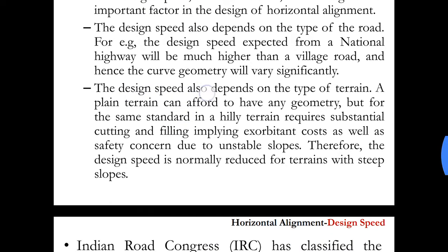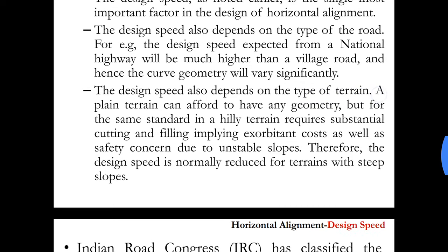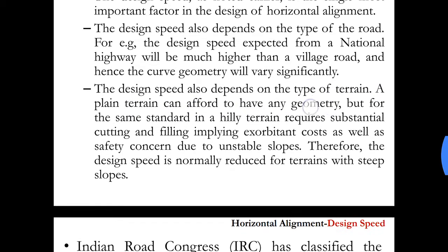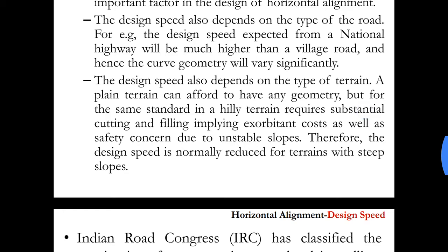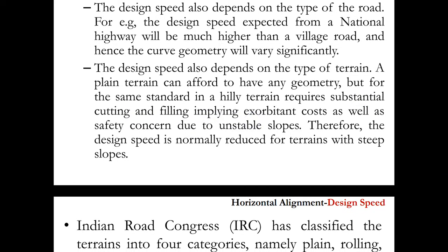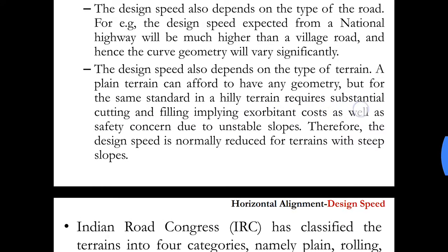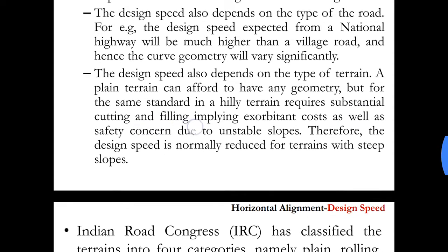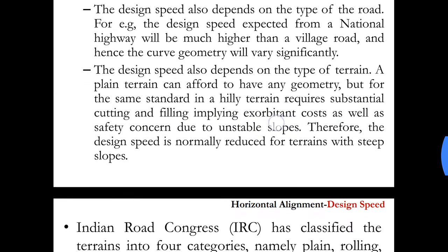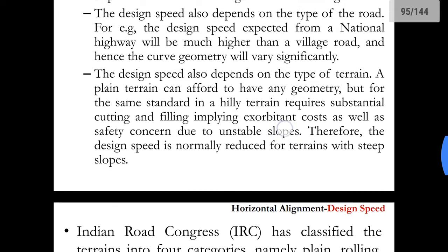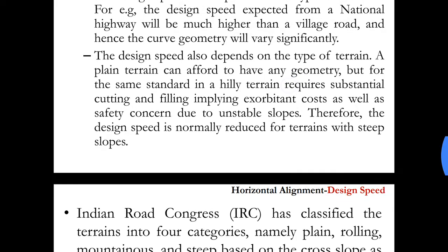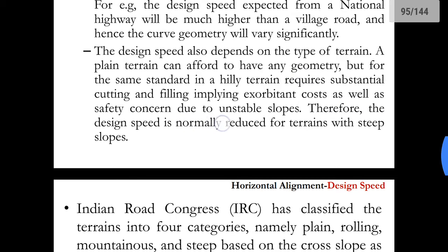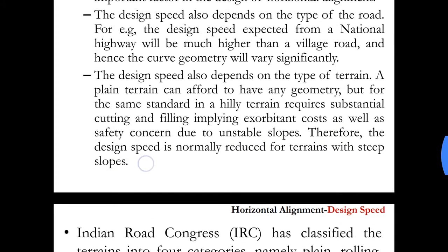The design speed also depends on the type of terrain. A plain terrain can afford to have any geometry, but for the same standard a hilly terrain requires substantial cutting and filling, implying exorbitant costs as well as safety concerns due to unstable slopes. As the slope value increases, we need to decrease the design speed. Therefore the design speed is normally reduced for terrains with steeper slopes.